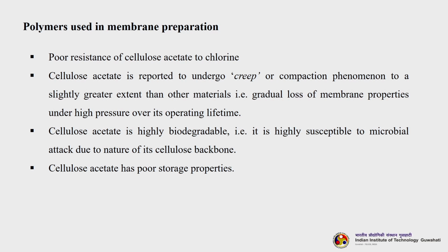Cellulose acetate is highly biodegradable. This is another big problem if you are using this type of membrane for bioremediation or wastewater treatment processes, or for the production of biopharmaceutical drugs. It is highly susceptible to microbial attack due to the nature of its cellulose backbone. Microbes will actually try to eat the cellulose as a source of glucose. So, cellulose acetate has poor storage properties.